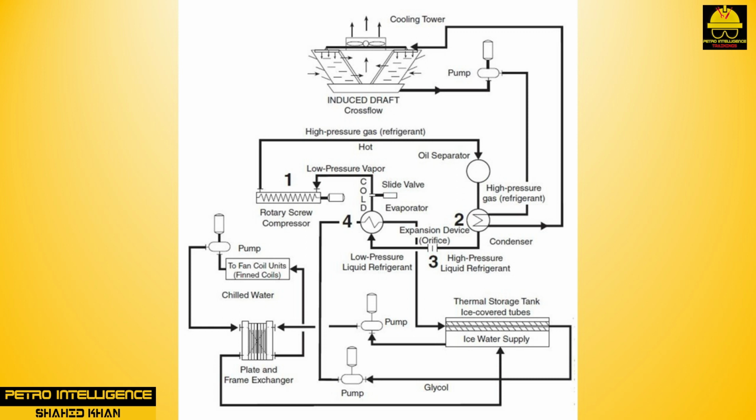Raising the temperature allows us to cool the compressed gas with water, and in this manner the propylene is liquefied. At this point, we have a supply of liquid at elevated pressure and at about room temperature. To make it boil, all we have to do is release the pressure under which it is stored since room temperature is far above its atmospheric boiling point.